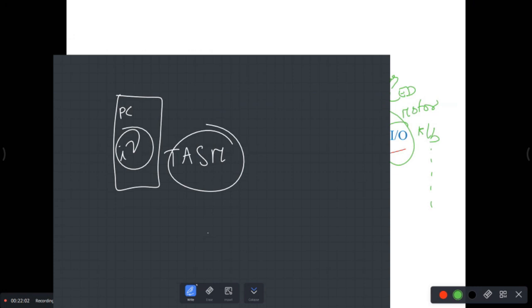The PC does not have 8255 interfacing on its motherboard. So what we did is, this PC has something called PCI slots. I don't know how many of you know about PCI slots. Your PC has PCI slots. On that PCI slot, we fixed a PCI board which has an 8255 in it. Go and refer to your manual. So we have used a PCI card in this.